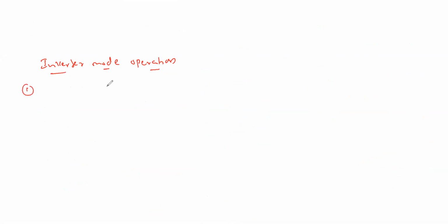First point: if load circuit EMF, or if E is negative and alpha is greater than 90, then the source E will feed power back to AC source.